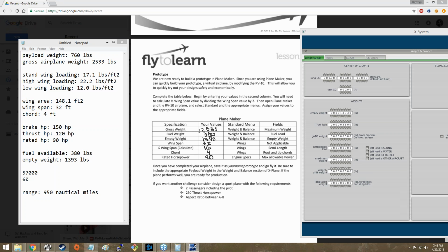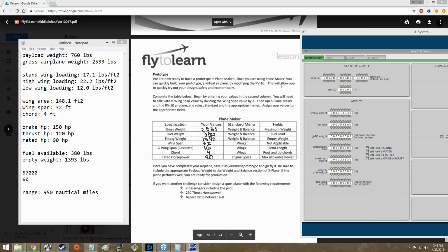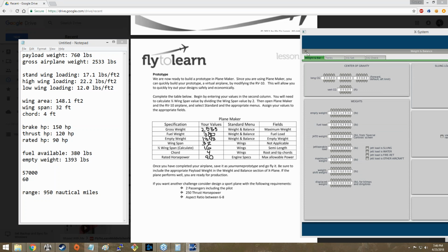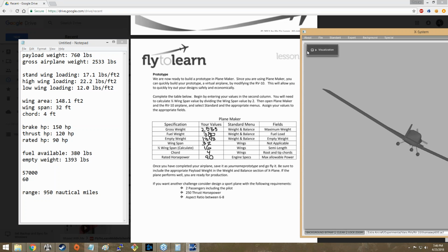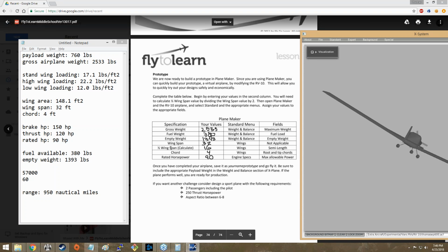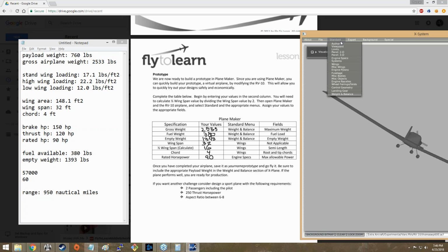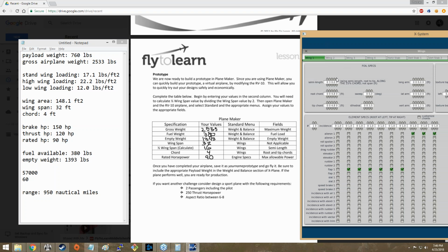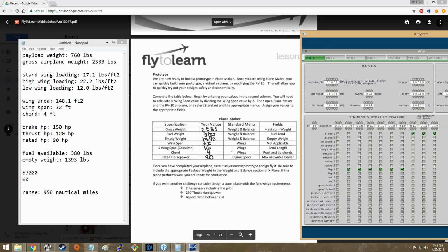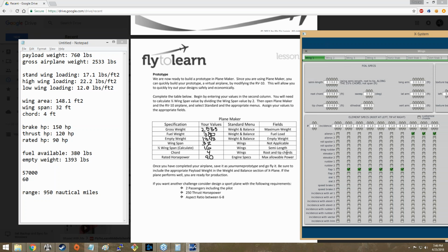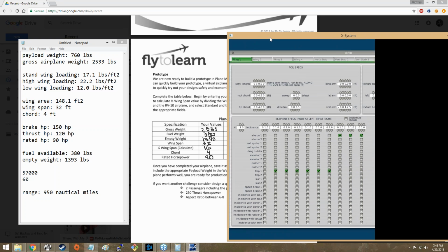Alrighty, let's get the rest of these values entered so you guys can spend the last of the time doing some test flying. So I'm going to close out the weight and balance menu. As we can see, the next values are going to go into the wings menu. So let's open up that menu. We've got semi-length and root and tip chords, which should be pretty easy.